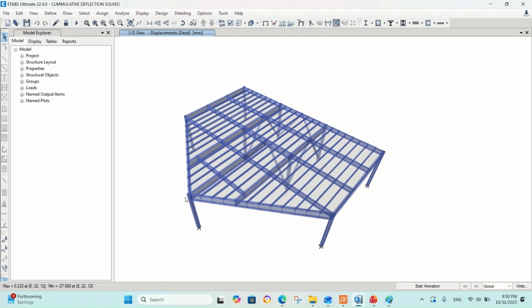So this girder now will be supporting these main beams, and it will significantly reduce the deflection, because now the load path is direct to the column and it will carry a good portion of this floor based on the tributary area for sure.